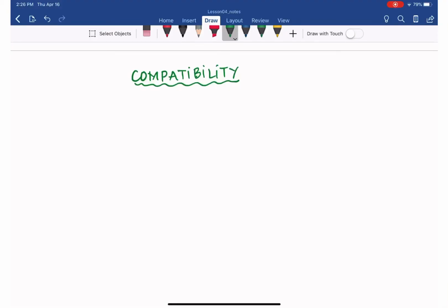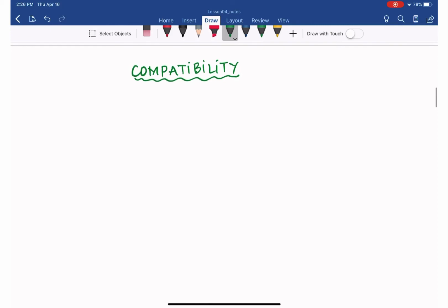So from that demonstration, you can see what I mean by compatibility and consistency. And now let's take some notes here. So compatibility, as you can see, is the requirement that after a structure has deformed, all of its deformations are geometrically possible. In other words, there can be no gaps or overlap. So let me make the definition here before we continue.